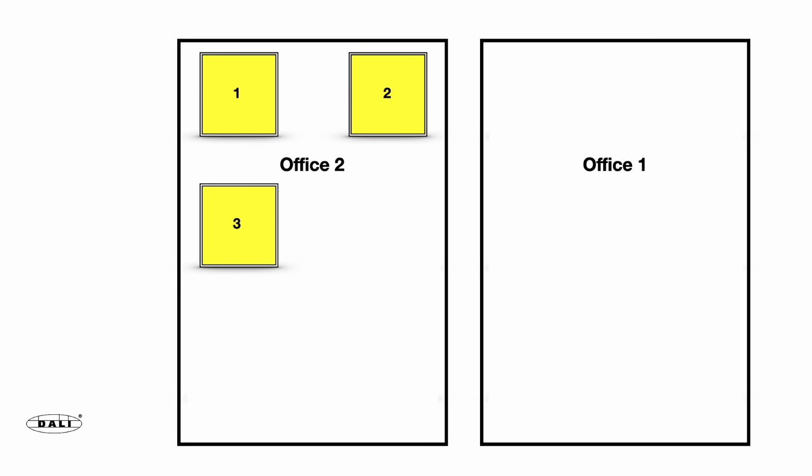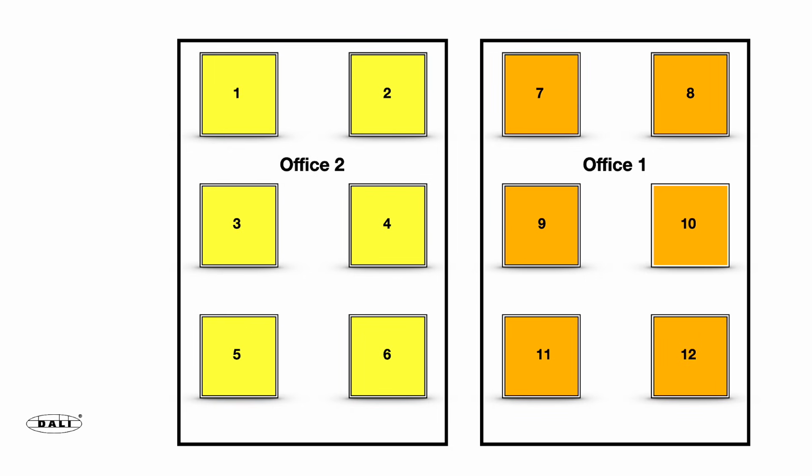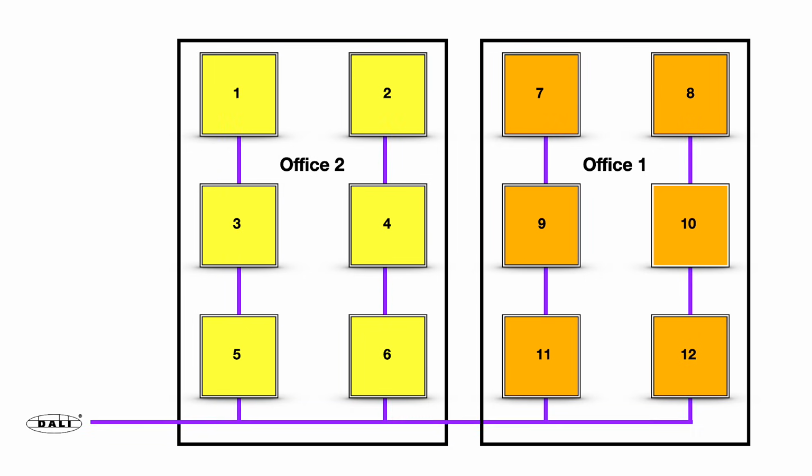So what is a DALI address? Every device on a DALI line, whether it's an LED driver or a fitting, is given its own number. Think of it like house numbers on a street. The controller sends a command to number 12 and only number 12 responds.